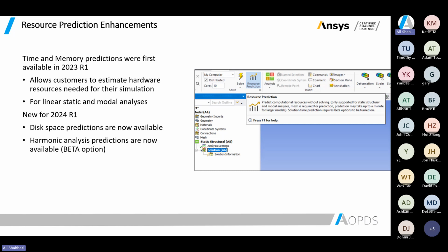And somewhere in the middle of the solve, I see that my disk space is becoming full, and then the model cannot continue solving, so it aborts with an error. And sometimes nobody knows how much temporary files are going to be written in your storage and how much storage you are going to need to run your simulation.